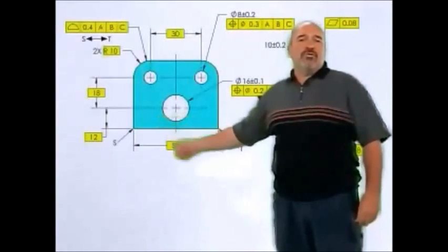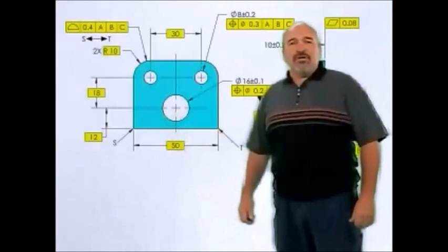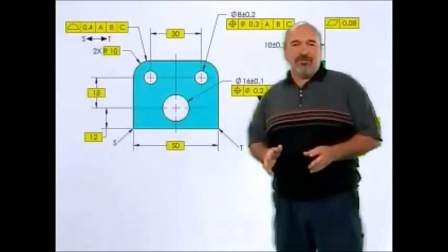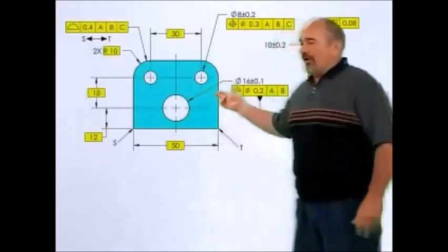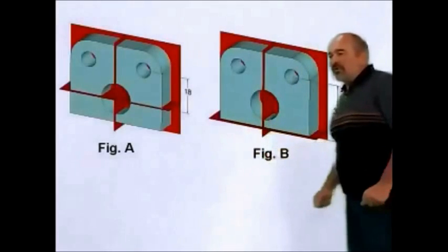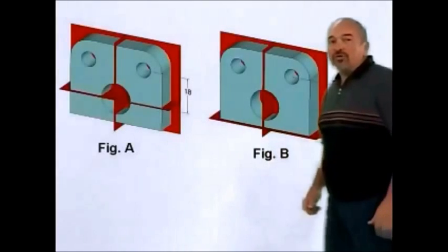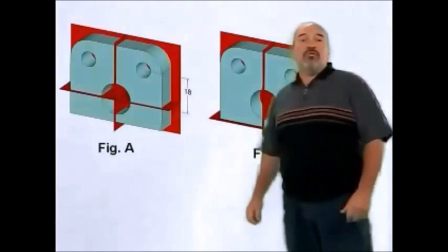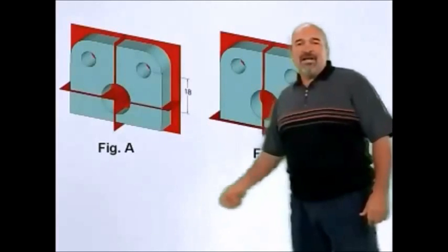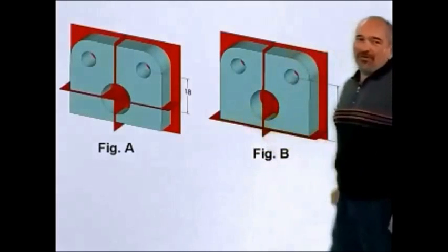Here's a little test that one of our faithful readers asked me to create. He tells me that 9 out of 10 folks at his work get it wrong. Given the drawing, does figure A or B more correctly illustrate the datum reference frame, which establishes the origin of measurement for the profile tolerance and the position callout on the 2 holes? If you said figure B, you are correct.